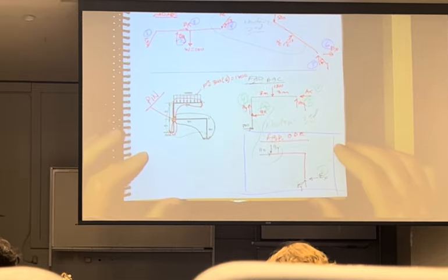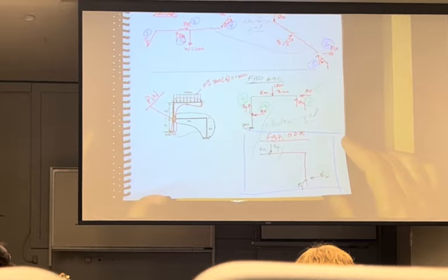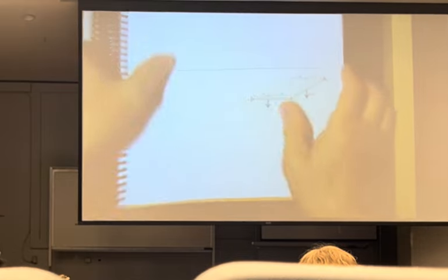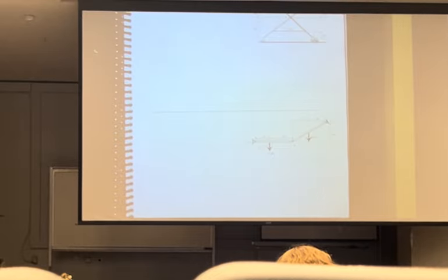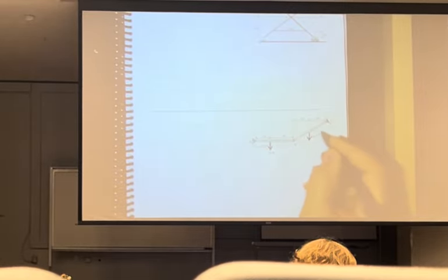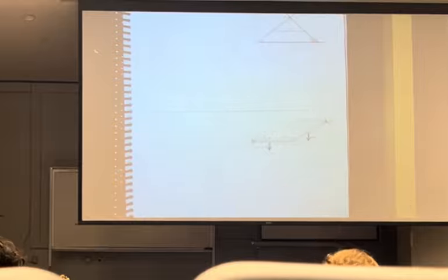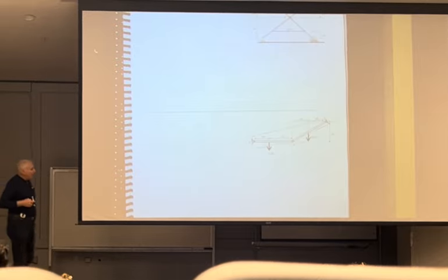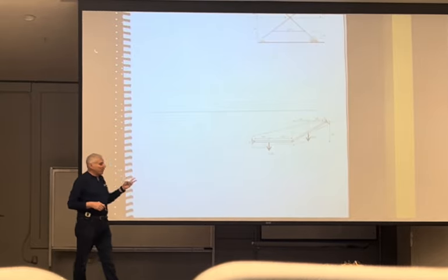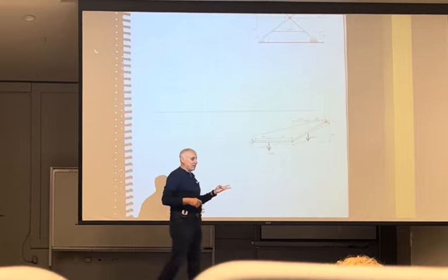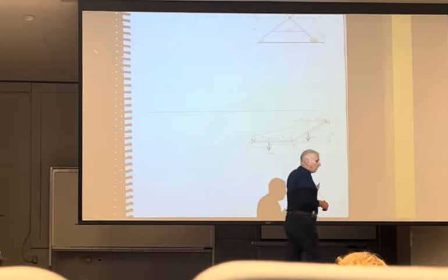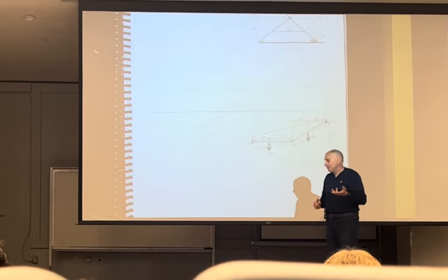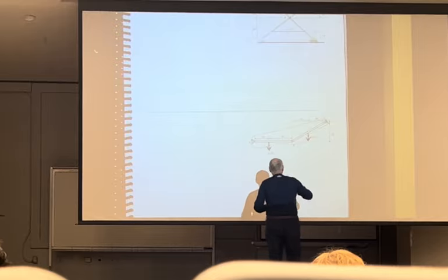Okay? Questions? Moving on. Draw the free body diagram of this one. Well, if I do this, although it's a free body diagram, it isn't appropriate. Why not? Well, I got 2 unknowns at A, 2 unknowns at C. That's 4 unknowns. I only have 3 equations. That's a problem. I have a pin at B.